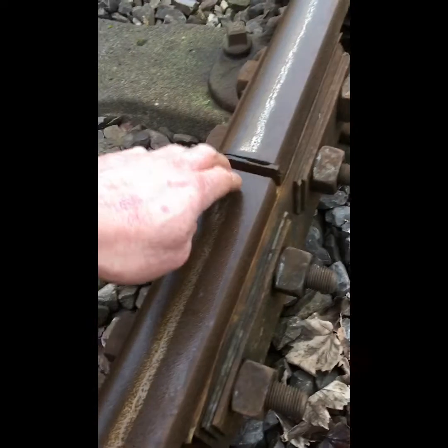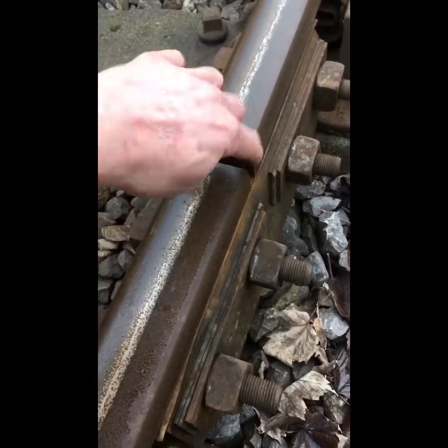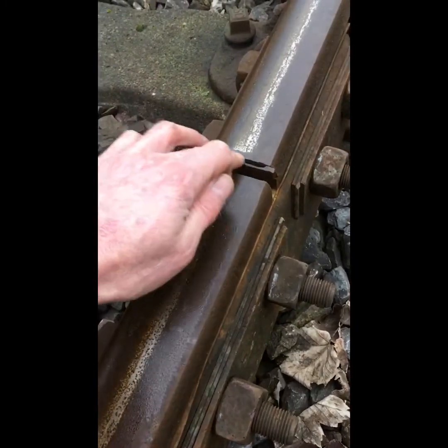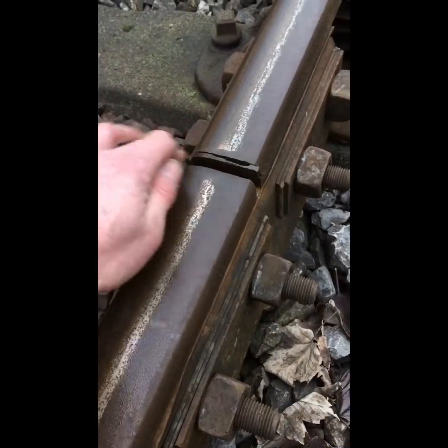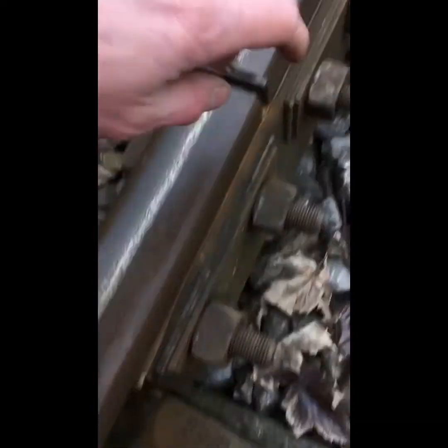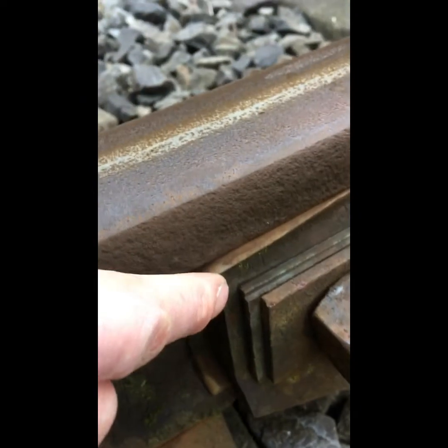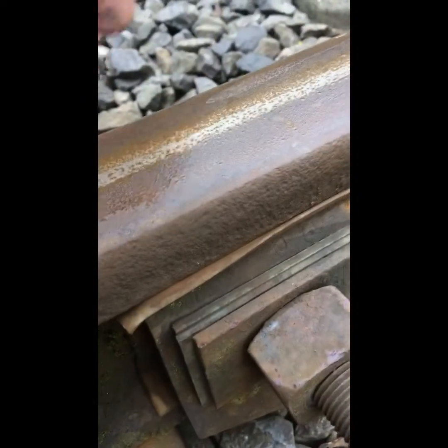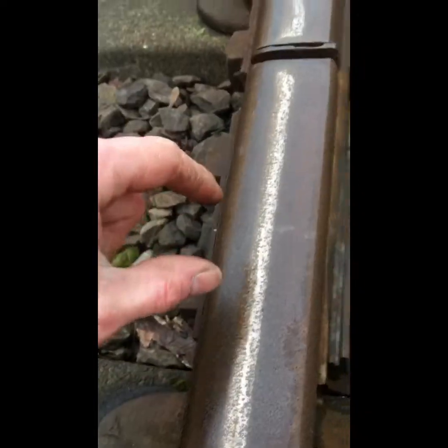Obviously, with block joints, the rail insulation piece in the middle there, called the T-piece, these do suffer with wear and tear from the locomotives and wagons and carriages over the years, and they do wear out. And also you can get movements on the side plates as well. As you can see on here, we have our main insulation and we have our backing insulations. The main plates themselves are on both sides, the insulated plates, they have a ferrule through.